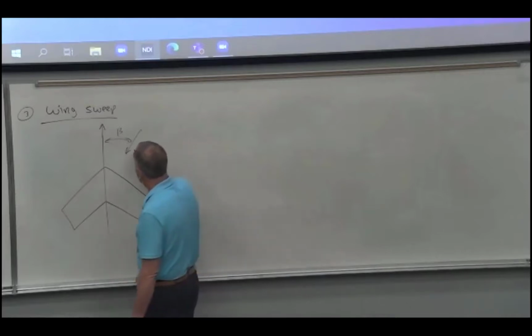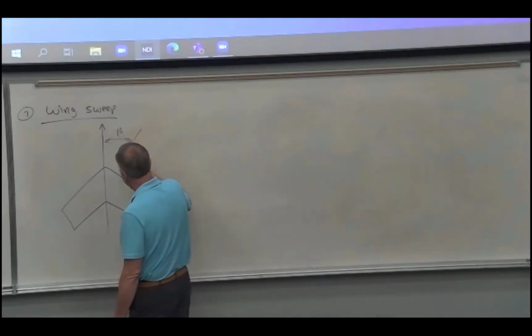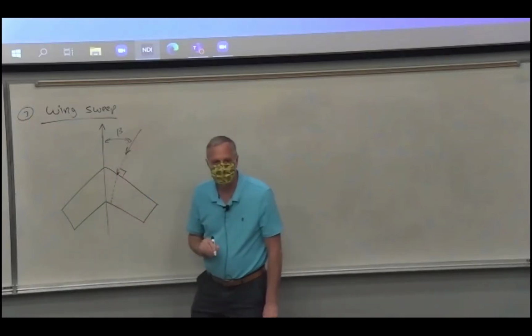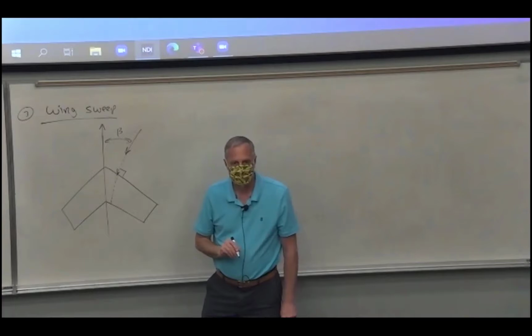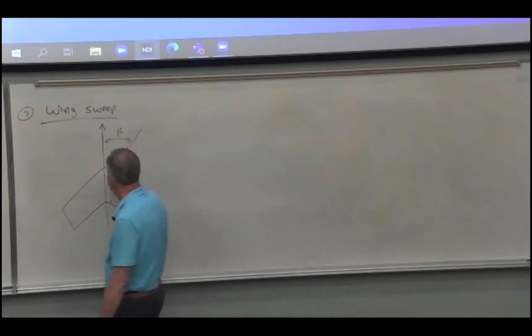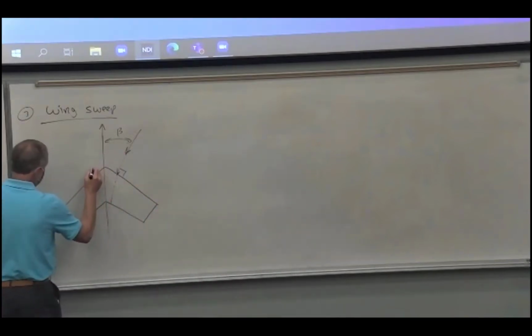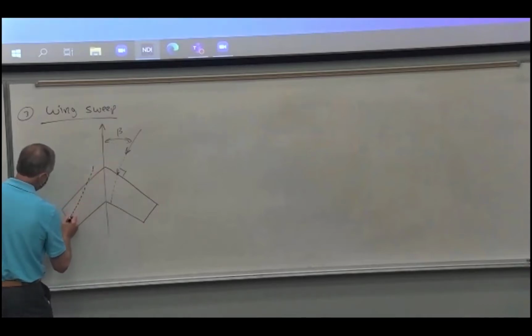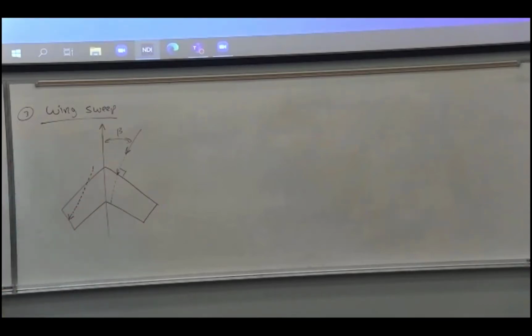You notice that when there's side slip, the airflow here pretty much comes into the wing perpendicular to the chord. Whereas over here, notice that the flow is pretty much span-wise. It's not really going over the airfoil of the wing. It's kind of just going down the wing.